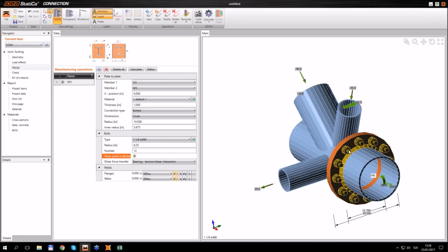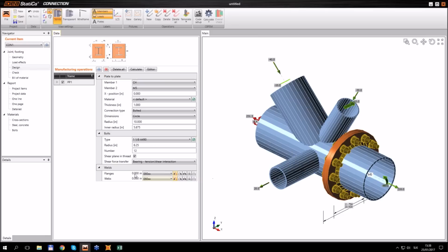And let's change the weld size and material. So I will adjust it to 0.375 inches, also the second one, and I will choose the material to be E100 in both cases, and we can continue with connection of the diagonals.